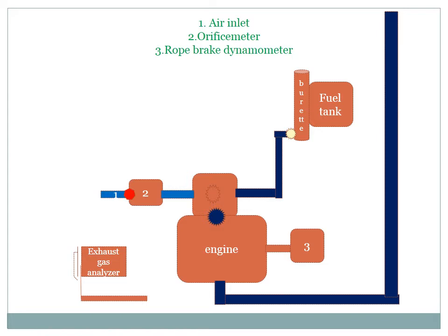So what is happening here is that the air from the air inlet is getting inside the mixing chamber. At the same time, the fuel from the fuel tank through the burette is let inside the mixing chamber. They get mixed and then it is allowed to get inside the cylinder at the inlet stroke. Now the combustion will take place inside the cylinder at the power stroke, and the exhaust gas analyzer is put inside the chimney. The exhaust gas analyzer is coupled with the computer, in which the pre-installed software will give you the smoke level and the amount and types of emissions coming at the outlet.